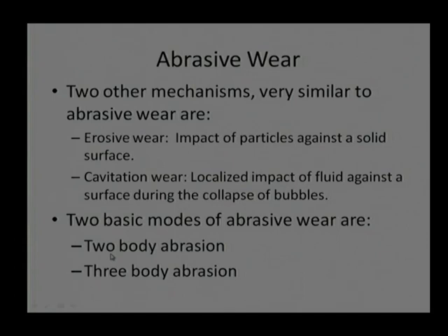Experiments show that two body abrasion is causing slightly higher wear rate compared to three body abrasion. And then, maybe again subjective, many times we have observed that three body abrasion causes only 10% damage compared to two body abrasion. So, a number of parameters are going to affect it: particle shape, particle size, or everything will matter when we talk about the abrasive wear by three body abrasion phenomena or mechanism.